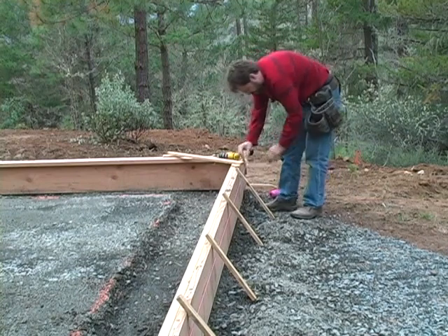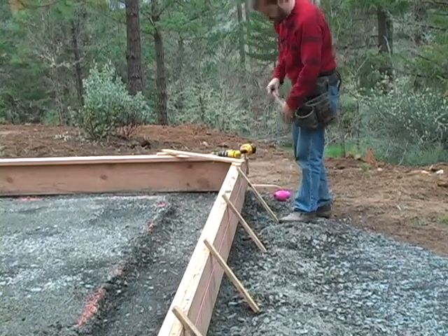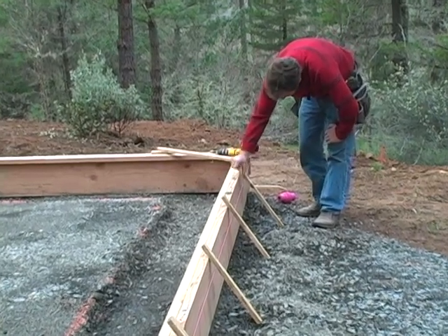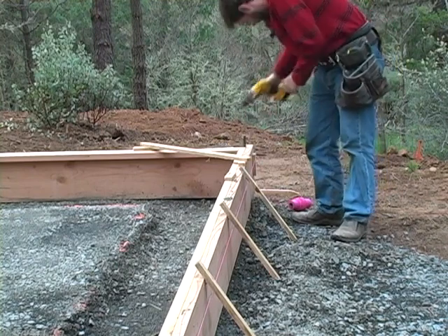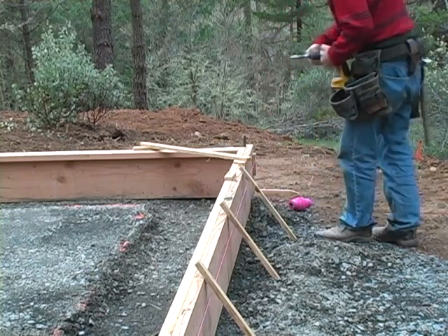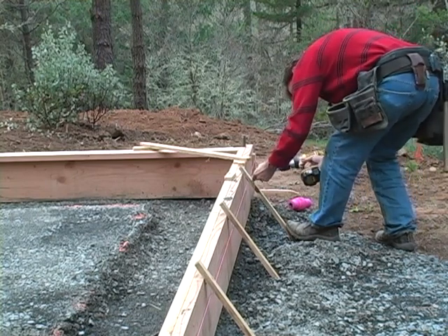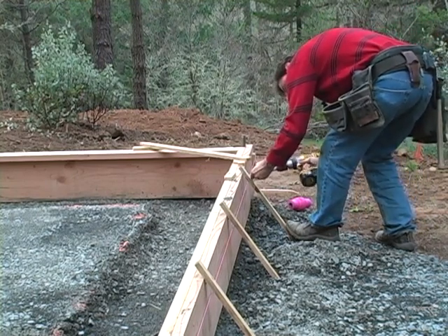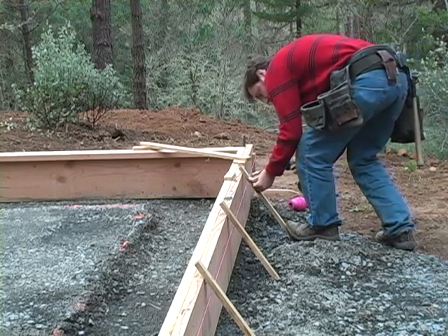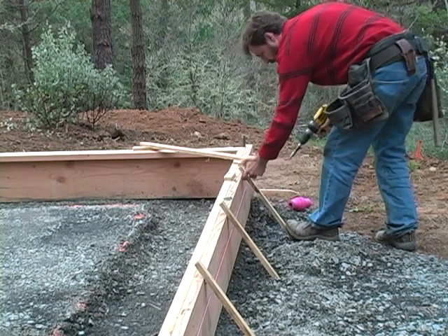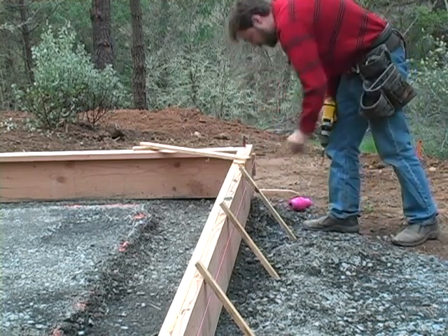Now I've gone ahead and braced this off every 3 feet all the way down the form board. And right now where it's at, it's just perfectly sliding right past that string. So I can secure this in place now. Again, I took most of the bow that was in this board out when I was around the middle area here. That's where the most flexibility in the board is. And that's all set.